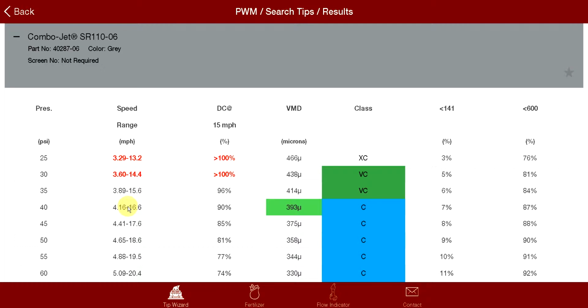On the flip side, so literally on the other side of the sprayer, where your other wing is slowing down more dramatically into like a straight corner turn, you might actually be going backwards. That reduction on your duty cycle on the bottom end is the way to maintain your flow rate a little bit lower on the areas that you need it, so that you're not burning crop on the inside of that turn.